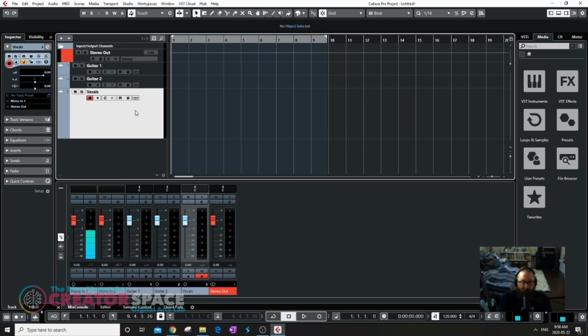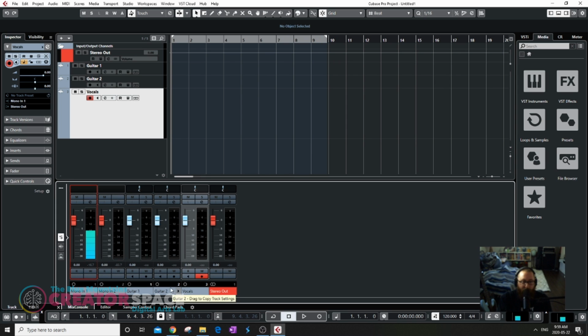So we'll do a quick little test just to show that that's functional now. Our vocal channel, we can see that it's working. We're not peaking the meter, so I'll reset that. The loudest I'm coming in is around minus 13 decibels. If I talk really loud, it goes to -4. So even if I'm talking super loud, it's not peaking the meter, and that's what you want.